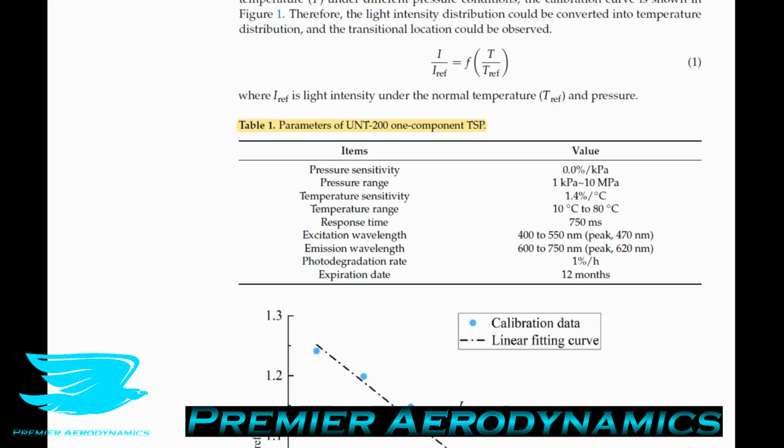Then this excites the electrons, and then they will emit 610 nanometer light. Depending on the temperature, that light will be brighter or less bright. To get rid of this 400 nanometer LED light, the excitation light, from corrupting the results, if we want to see the resulting light, we have to use a high-pass filter, a filter that will block out anything lower than 580 nanometers. So we can just get the light that the cascade is now re-emitting.